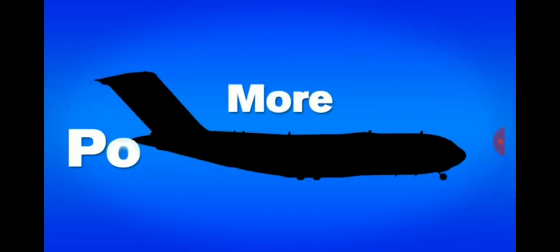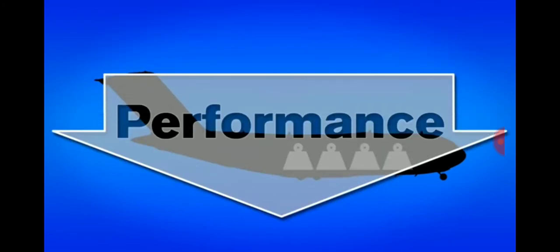Another factor to consider in the performance of an airplane is its weight. Heavier airplanes require more power and thrust. Simply put, the heavier the airplane is, the lower its performance would be. For takeoff distances, a heavier airplane would need more distance in their roll. This is because it takes more power to get the airplane rolling and accelerate to rotation speed.